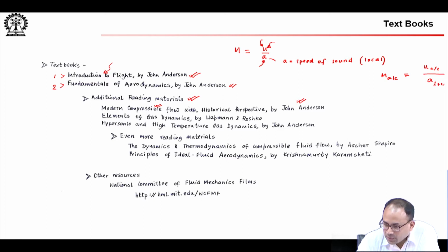So, what does local speed of sound mean here? It means you have to go to that altitude and find the temperature, because you will see that the speed at which these small perturbations in velocity and pressure, etc., move around is related to the local temperature. So, A for most of our applications will be given by the square root of gamma RT.